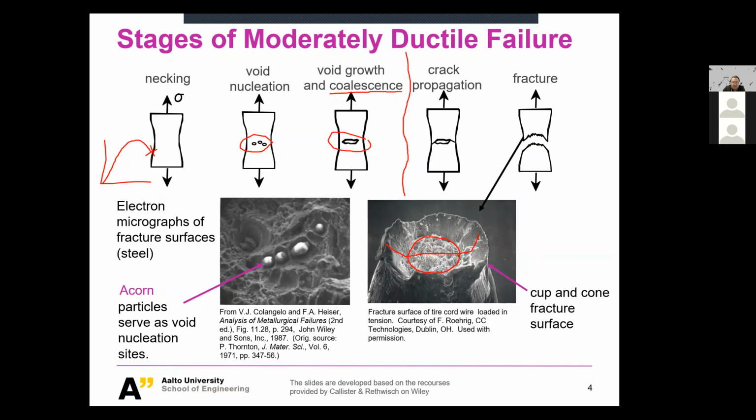So still look at the surface, you see, here you can really find what are the voids I'm talking about. Here you don't see it during experiments, but after fracture you could see. So let's see, this is kind of one void. Of course you just see half of it or a part of it, because the other side is on the other part of the broken specimen.